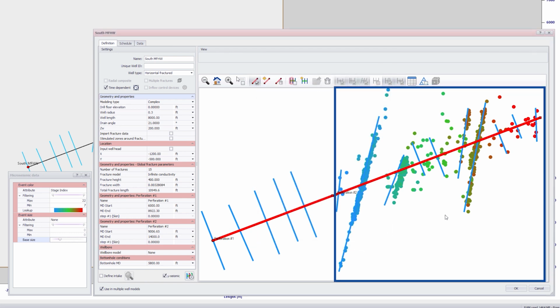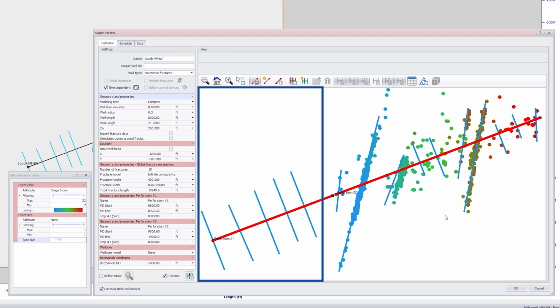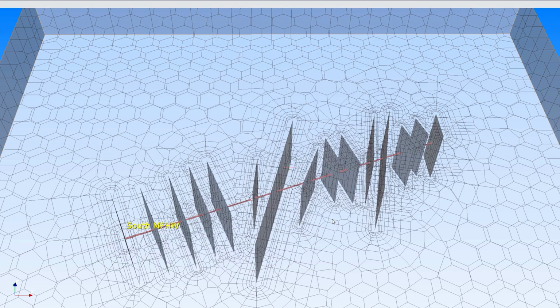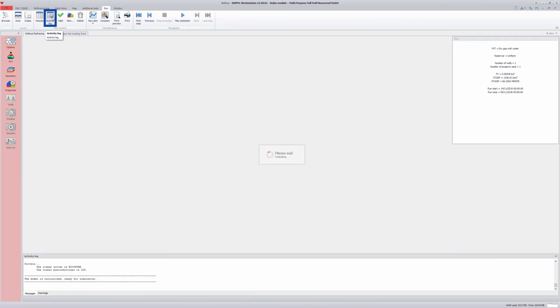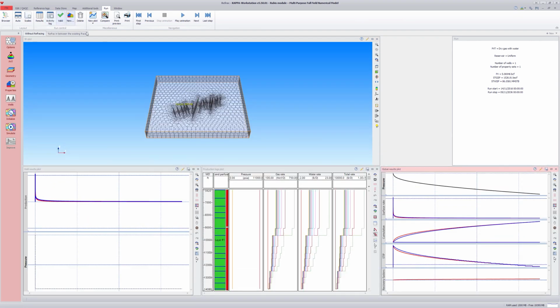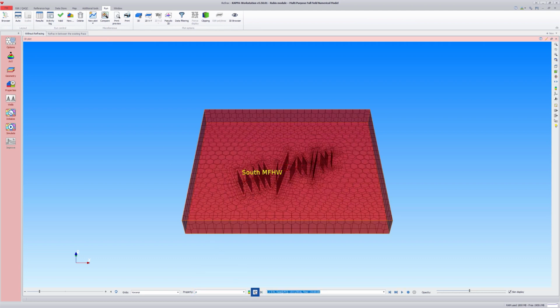For this case, perforation 2 and the original fracs open at all times are kept. As there is obviously no refrac job in the first instance, perforation 1 remains closed at the outset. Back to the Run tab, a simulation is run to forecast the model based on a constant bottom hole pressure for 20 years. Once the simulation is complete, maximize the 3D plot to play back the pressure fields.